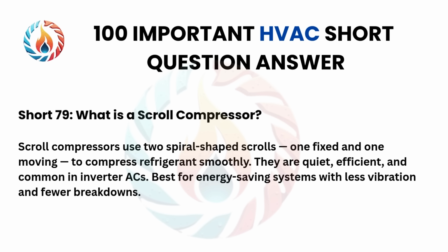Short 79. What is a scroll compressor? Scroll compressors use 2 spiral-shaped scrolls, one fixed and one moving, to compress refrigerant smoothly. They are quiet, efficient, and common in inverter ACs. Best for energy-saving systems with less vibration and fewer breakdowns.